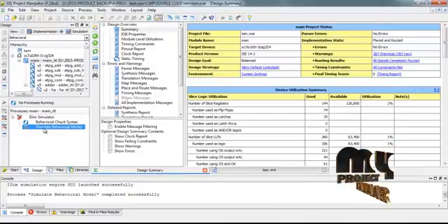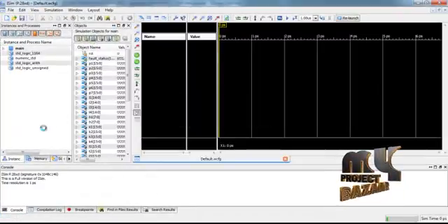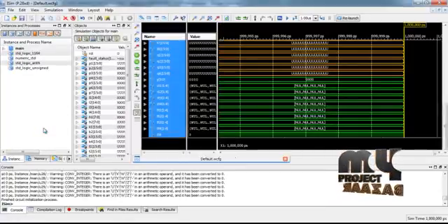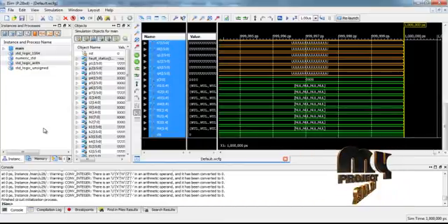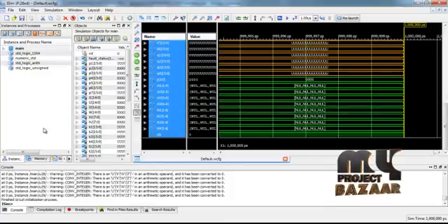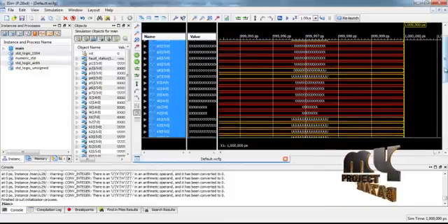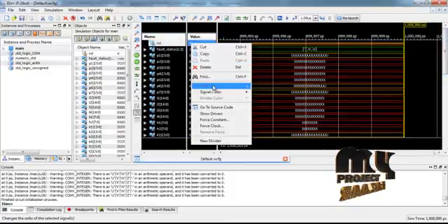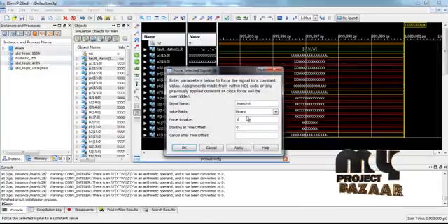This behavioral model represents that every time we apply the clock input signal and pass the data one by one, it produces the test output data, compresses the output data into string conversions, compares with the present and golden signatures and produces the output data bits. Then we apply the reset function as 1.